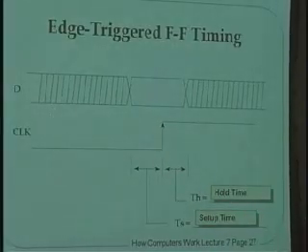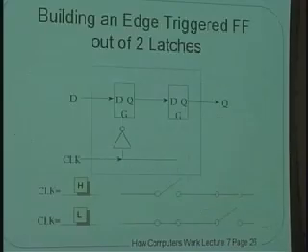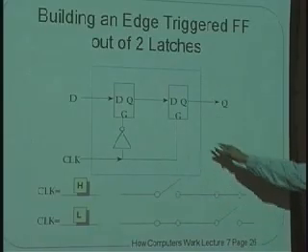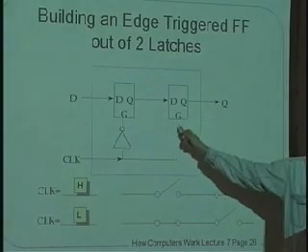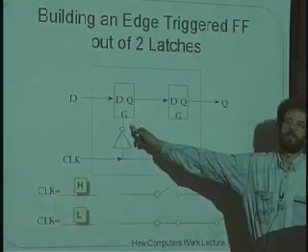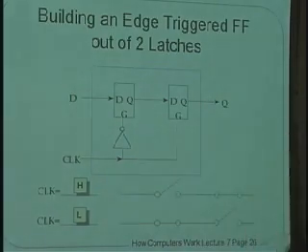Does the fact that in one case it has to flow through an OR gate and in the other case it doesn't present a timing problem? Yeah, it turns out that you have to be a little careful about the overlap of the two G's here, okay? And in general, you want the signal on the second one to happen a little bit sooner compared to the first one. And if you want to, you can work that out. That doesn't matter right now.